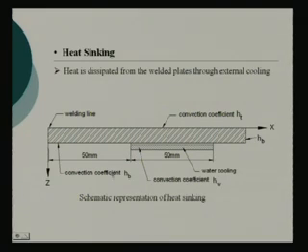For analysis of this kind of system, you will have to play with the convection coefficients essentially. The heat input is there and the material has a particular thermal conductivity, only the convection coefficients are changing. On the top you have a convection coefficient, and at the bottom another convection coefficient, probably these two can be the same because they are in the normal air medium, and here you put a convection coefficient of whatever cooling medium you are putting, right. Thereby you simulate the situation of water cooling, right.